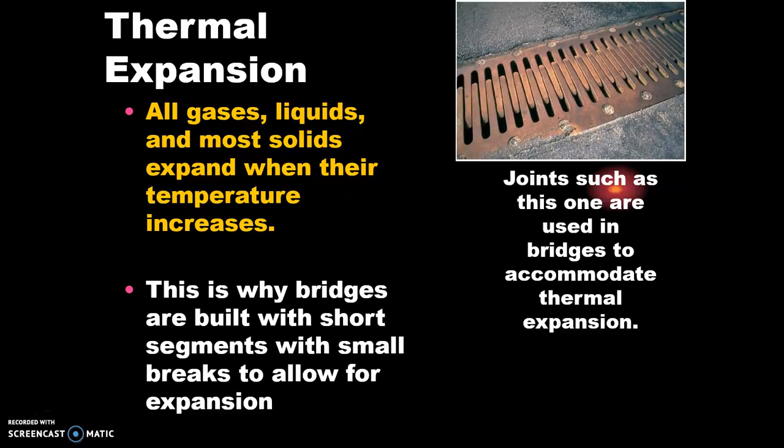So in the summer they expand, and these gaps will fill in and be tighter. When it's colder out, they're going to contract, because that solid is going to take up less physical volume by a very, very small amount. This joint just allows for that expansion and contraction to happen without any gaps that are going to be dangerous, or any damage caused to the structure.